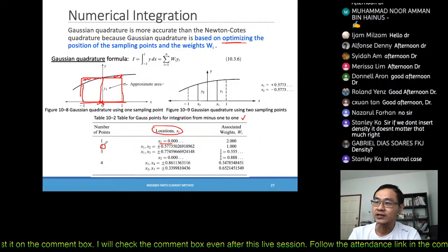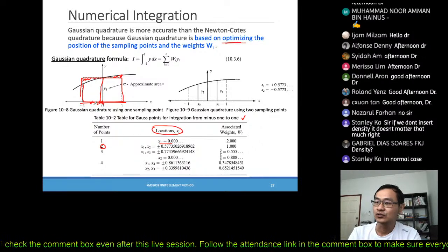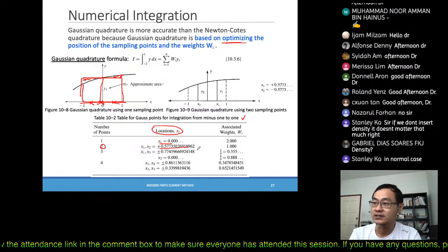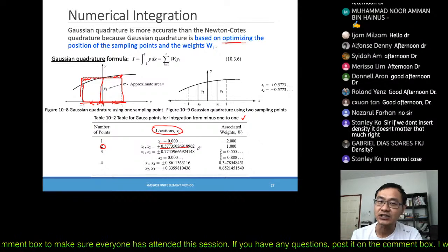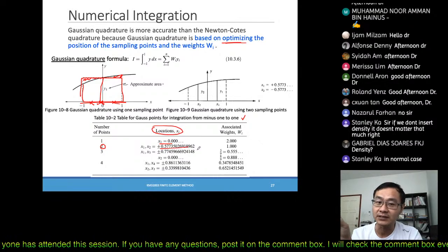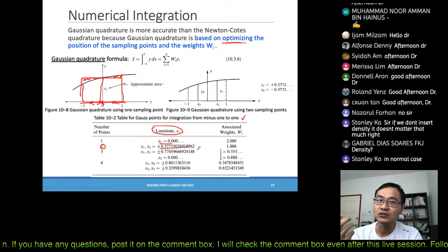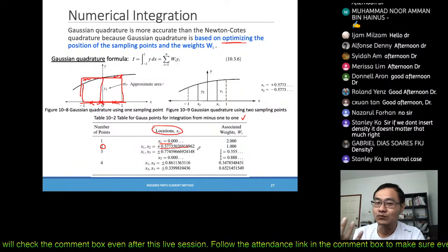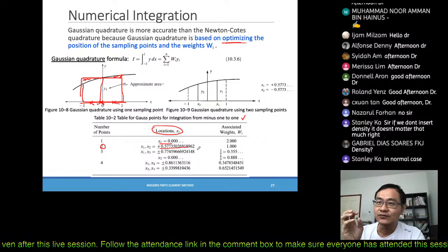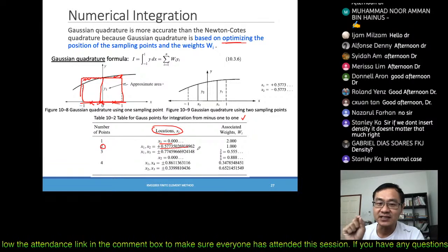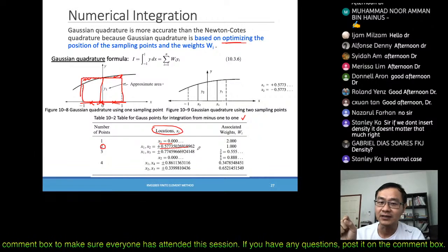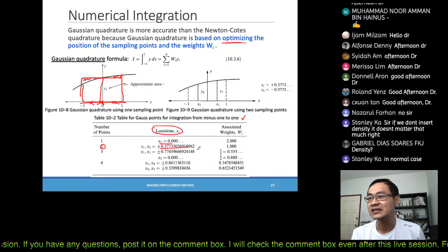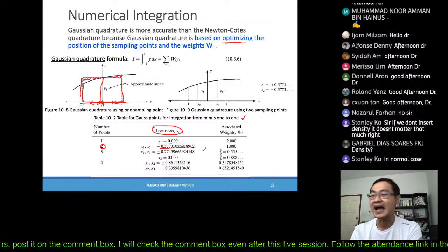Gaussian quadrature, then there will be 2 points, given by this formula, right? This constant. Therefore when they do the integration, they're actually computing at that particular point. So whatever stress, or displacement, but I think mostly it's stress, when we get the stress from the software, it's actually computed for every single Gauss point, or the integration point. Not necessarily Gauss, it can be called integration point, right?